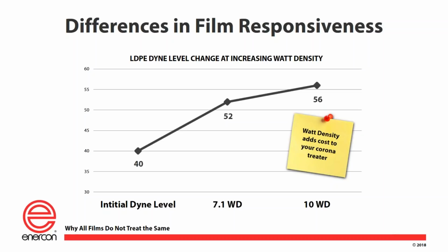I have a particular film, it's a particular width, it's on a printing press. The film comes to us pre-treated. My customer tells me that they have to have a 56 dyne on this material, and that's part of their spec to us. You know, we're converting the film for this end user, and the end user tells me I have to have a particular dyne number.